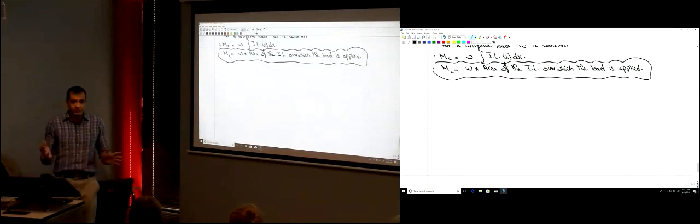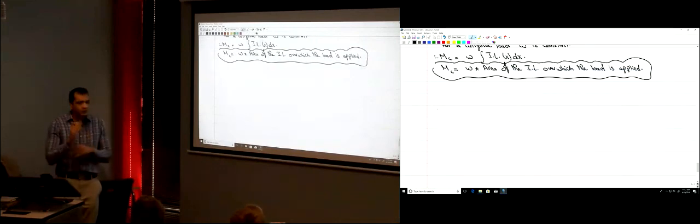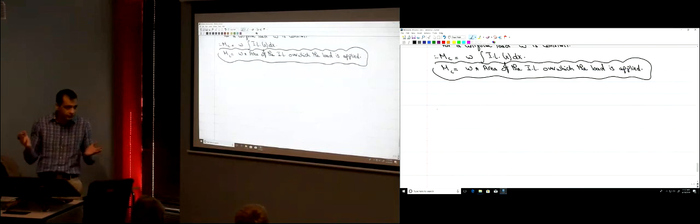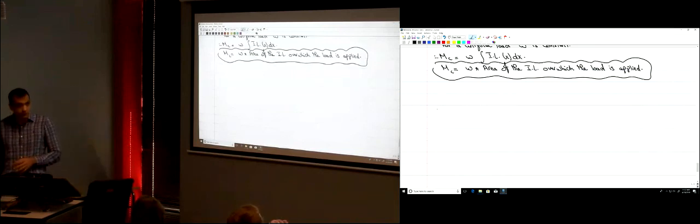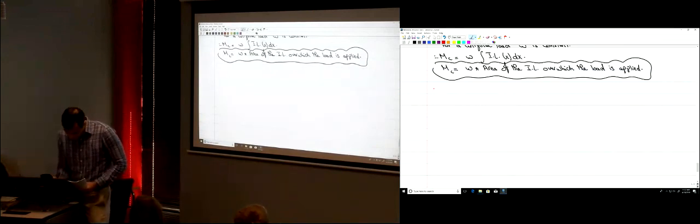This rule applies for everything. When you have a uniform load for any function, just W multiplied by the area of the influence line for that function over which this W is applied. So let's see an example over here. Very, very nice example.